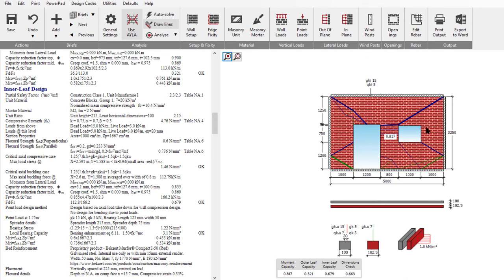Now the second thing is, why are some of them very thin and some of them very thick? The thickness is to do with the degree of rotation, to do with the degree of moment, plasticity around that. So once it cracks, it's got its plastic moment, but the thicker ones have rotated more, so they're the more dominant ones, as you would expect.